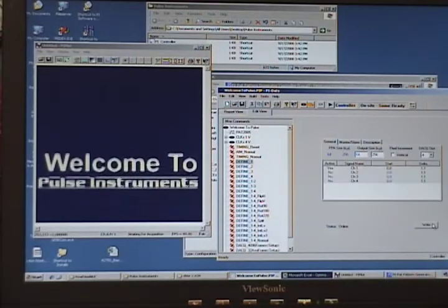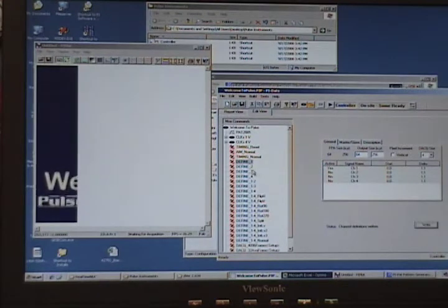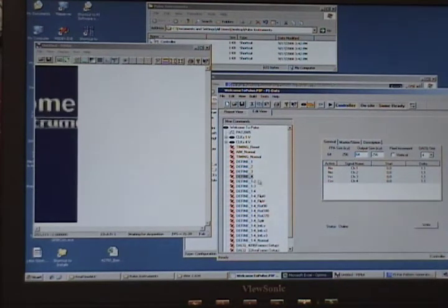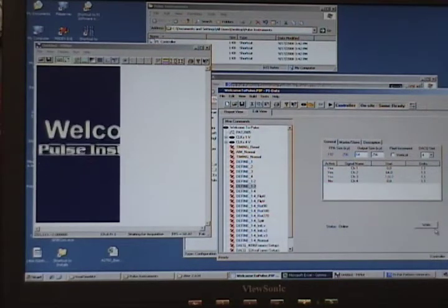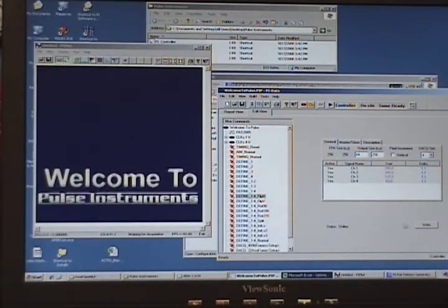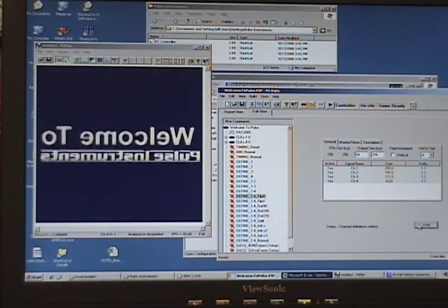Within the data acquisition system, I also have flexibility to turn each of the channels on and off. The digital multiplexer card is also a 4-to-1 switch, so I can use my software controls to turn each of the channels on or off. I can look at any one of the 4 channels, or I can say 2, 3, or 4 channels stitched together.